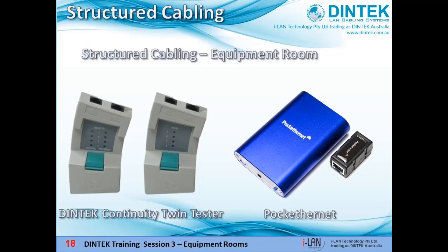There's other gadgets that can help with testing cables, like the simple continuity tester on the left here, which tests for stuff like open circuits and reverse polarity. That is, wires not punched down properly or that you might have got back to front. Then you get into expensive Fluke testers for testing throughput, crosstalk, noise and so on, but there are some relatively cheap gadgets on the market, like the PoE Ethernet network analyzer on the right here, which is great for use on smaller jobs that don't require performance certification.